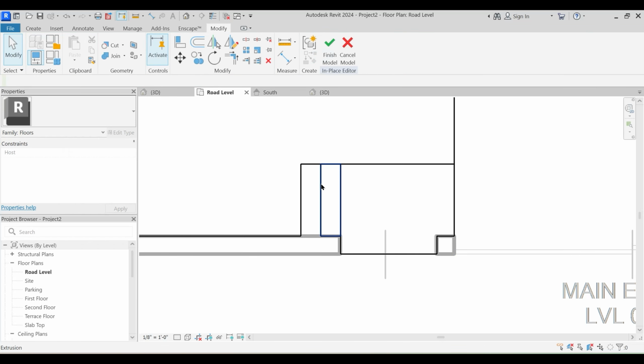Perfect. Okay, so select this, CS, that is create similar, and with that, just pick lines and select this. Take this wall all the way till here. Again, you see the constraints have changed. Let's just delete this. Just change the constraint from parking till upper ground floor and pick lines.